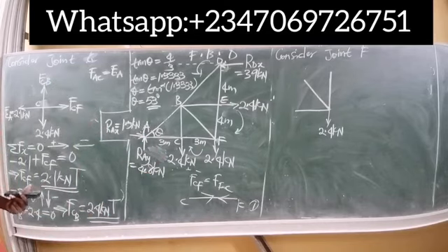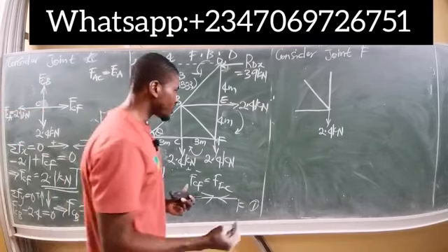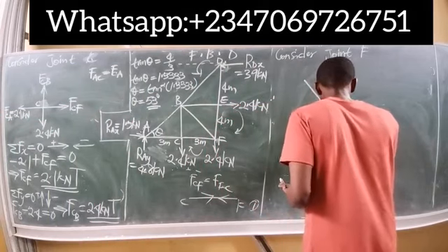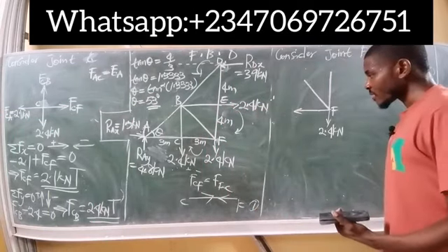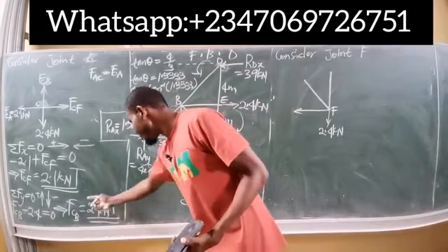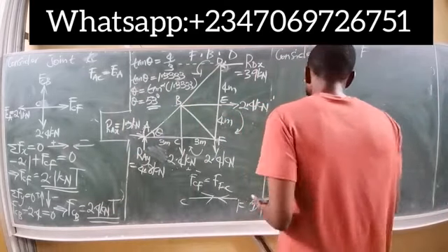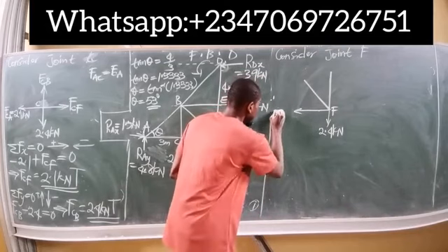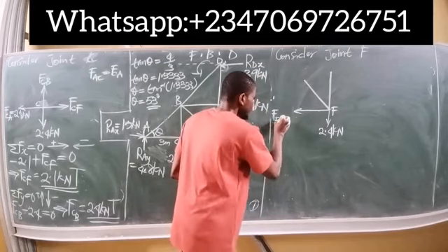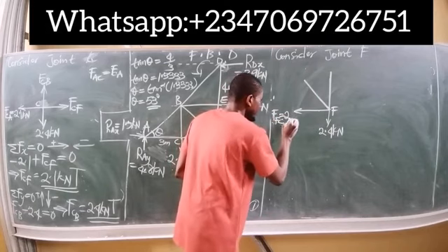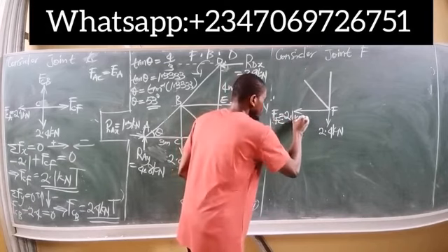They are equal in magnitude but opposite in direction. This is joint F, this force is pulling out of the joint, and we know the value. The value is simply 2.1 kilonewtons, FCF here. So the force at joint F relative to C is still the same thing as FCF, which is simply 2.1 kilonewtons.